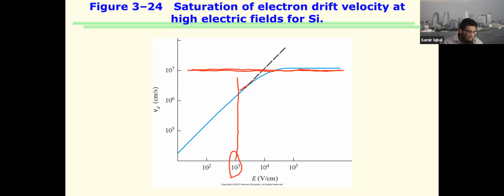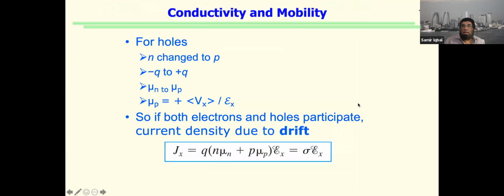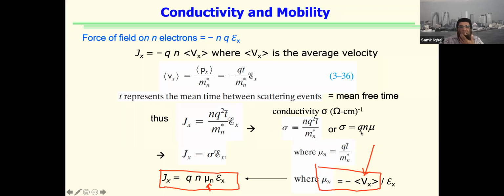So drift velocity then limits the overall drift current density. Now if I take you back to this also, you would see that mobility has dependence on average drift velocity. But if average drift velocity becomes saturated and cannot keep on going up with field, which means this also has an upper limit because of this guy again.